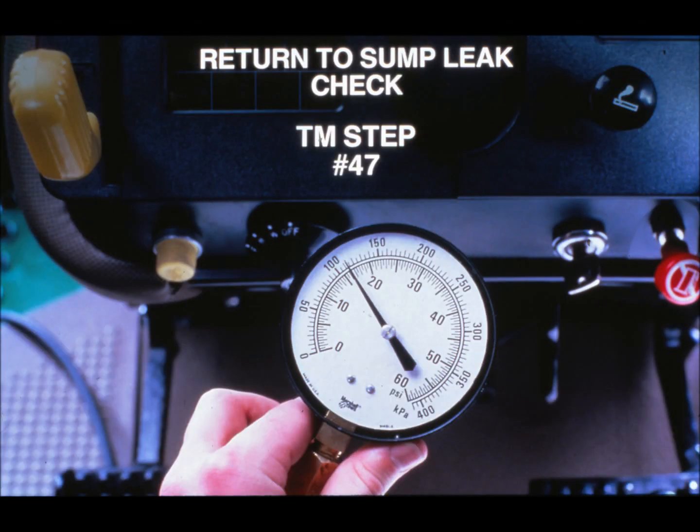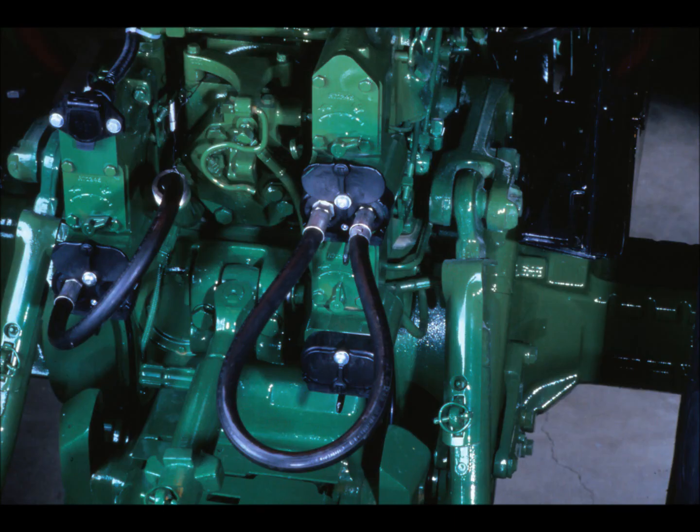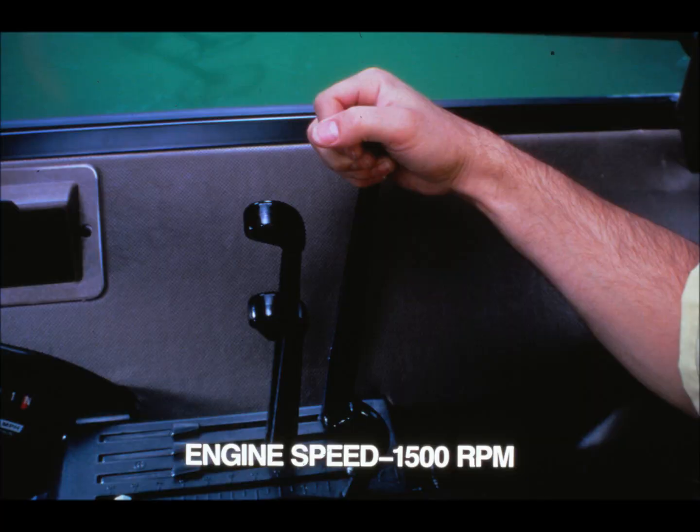Step 47, checking for leaks from return to sump, uses the lube pressure gauge again. Record lube pressure at 1,500 RPM. Turn the SCV metering lever to the maximum flow position and connect a jumper hose across the SCV. Pull the control lever to circulate oil through the SCV and readjust the engine speed to 1,500 RPM.